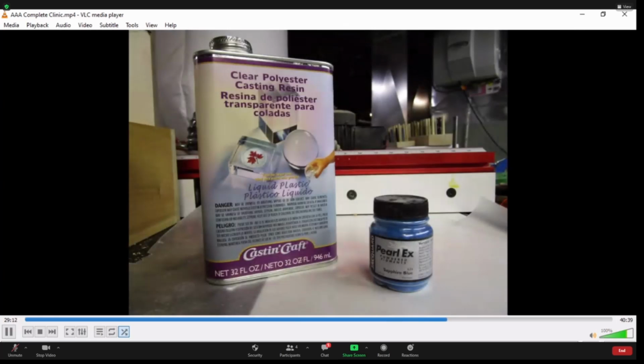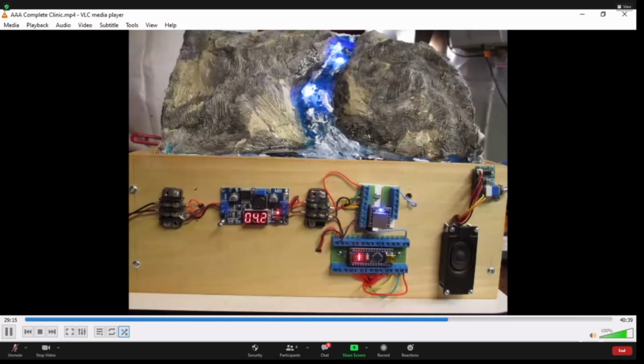I let the resin sit for about 15 minutes until it was as thick as syrup, and then tilted the structure and made the first pour all at once. Within a minute, it was no longer runny. I pressed in a few rocks and twigs and let it harden overnight. The next day, I drilled 9 1/8-inch holes into the feature.